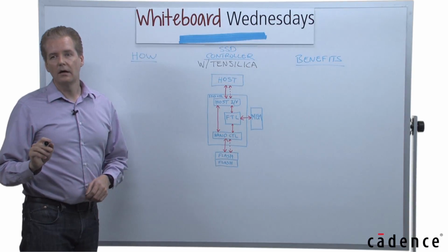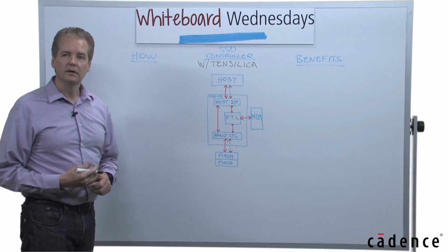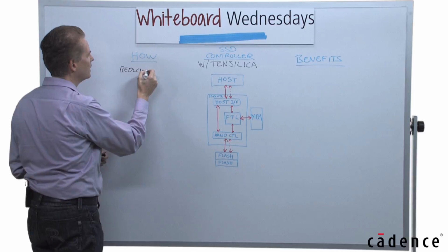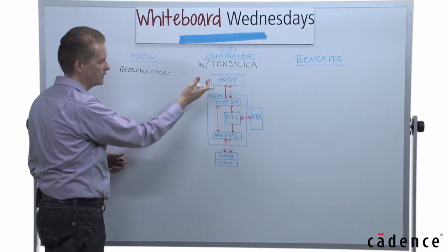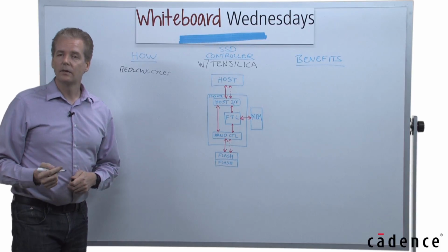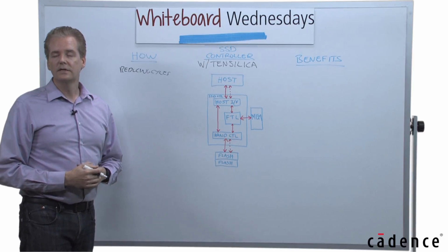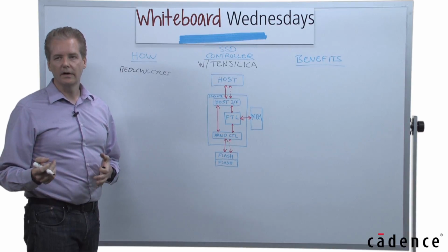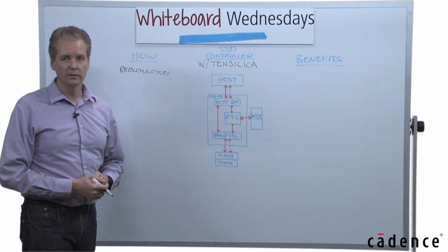One of the biggest requirements, the biggest trend, was high performance and low energy consumption. Now, really the only way you can do that is by reducing the cycles required for all of the processing that's happening between the host and the flash itself. Now, the obvious way to do that might be to offload that with RTL. And that works, you get very high performance and low energy, but you do have to spend more time developing it and also verifying it. And in addition, you're reducing the amount of flexibility that you have because it's less programmable.